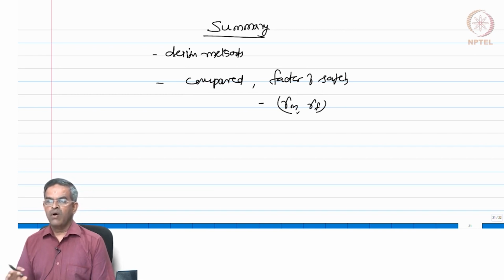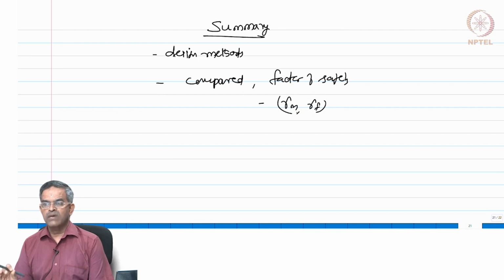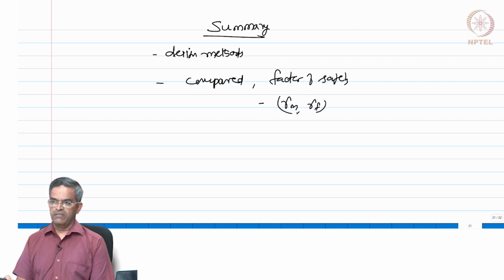All the time, remember friends, the geometric stability of the structure even under accidental worst scenario should be guaranteed. There is no design procedure which is acceptable by any courts of practice in the world which says that the geometric stability can be overtoppled at the cost of increase in load carrying capacity of the member or the material usage effectiveness.